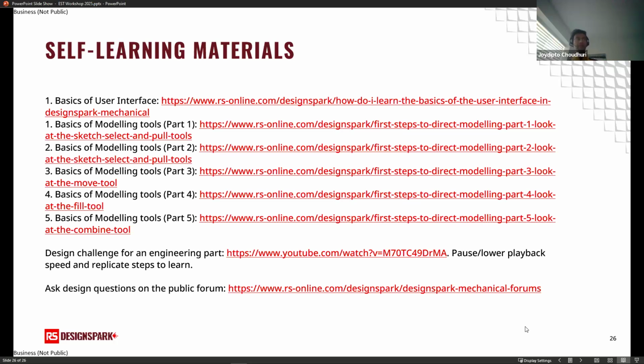It is. In terms of being 3D CAD modelers, SolidWorks and DesignSpark do share a common design paradigm, but the SolidWorks modeler is something called a parametric modeler, also known as a history-based modeler, meaning you control your dimensions on the design. So you need to set up your dimensions at the start of the design and then work forwards. But in DesignSpark Mechanical, you can freely model. You are not set by constraints. Like I showed you, you can have a free set of measurements. It's easier to build an early concept with DesignSpark Mechanical.